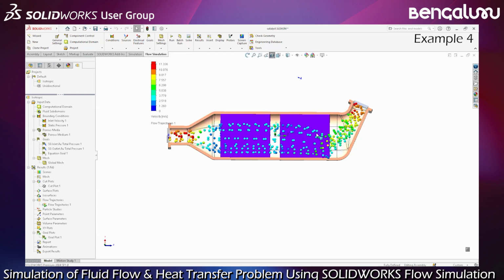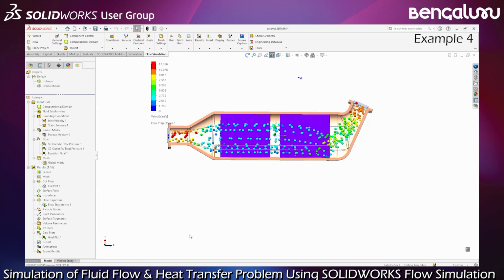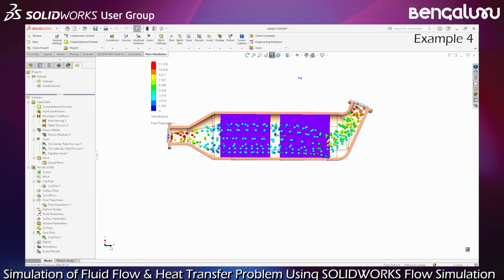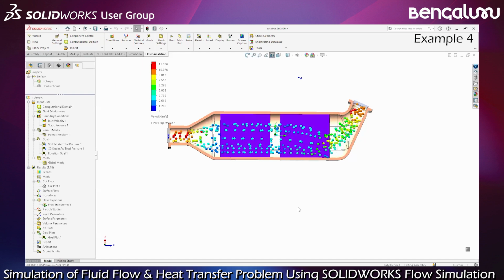And sometimes it is interesting to say I have a main direction, meaning there is no flow in the X direction for this case, only in the Z direction. You can see here what can drive the flow in one direction only. So this is something that you can define in the properties of the porous media.